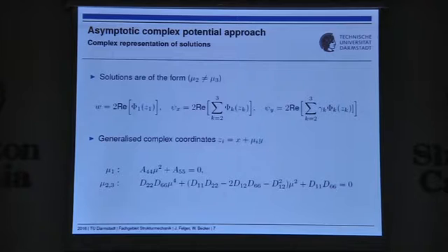So, without going into detail of the derivation, the general solution can be written in such a form with potentials. The derivation was basically based on the Lekhnitskii formalism, and these three complex potentials depend on so-called generalized complex coordinates, with these mu's here being the roots of these two characteristic equations. It has to be mentioned here that this formalism degenerates for isotropic material behavior, but considering a small artificial anisotropy, also the isotropic case can be approximated very well.